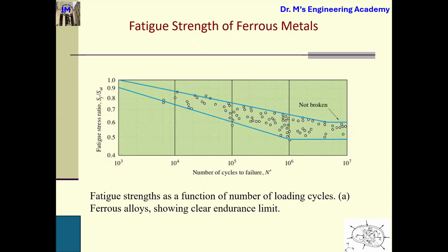For example, if the bending load is much higher than the axial or torsion, we use the bending one. Similarly, if the axial loading is very high, we use that, and if the torsional loading is much higher than the other two, we use the torsion one. Make sense?